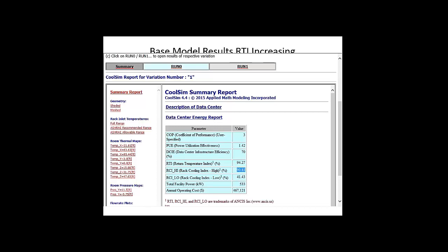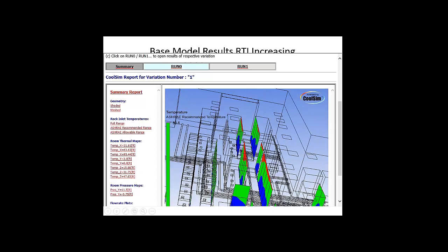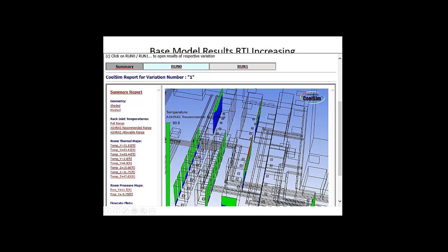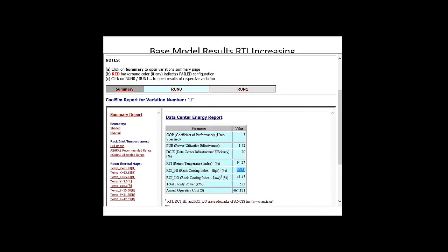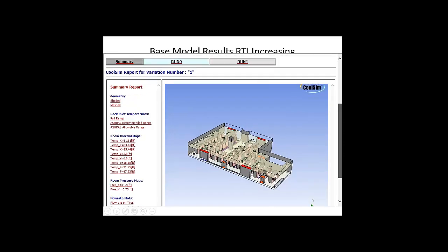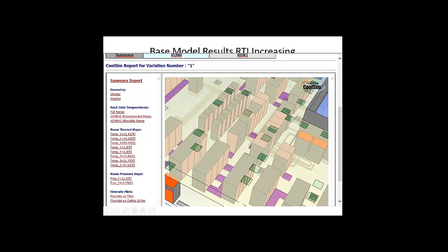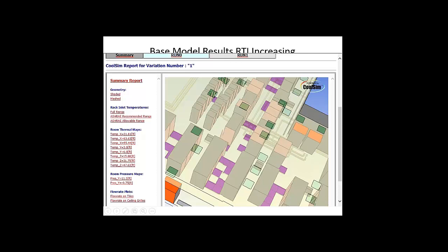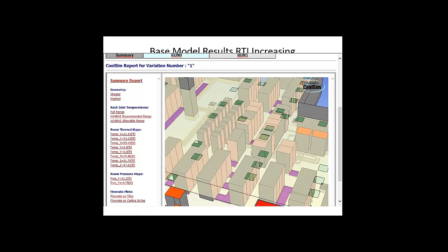And you can see that right here on our recommended plot. These are rack inlets. And you can see again what's going on. Same issue. Now, it's in that region I was talking about before. A couple things about that region. Notice that these racks are aligned with each other. So we've got an inlet here, and chances are we're recirculating. The other thing about that particular design right there is there's not a lot of perforated tiles that I notice. If we just look at the geometry alone, which is shown here in this representation, we'll zoom in a bit here, and I'll show you that there's no perforated tiles really there either. So I'm not exactly sure why, but in this region right here, we don't have enough perforated tiles. There's also pipes and so forth under the floor there, so that's going to be problematic as well. But certainly adding some perforated tiles there would be helpful.